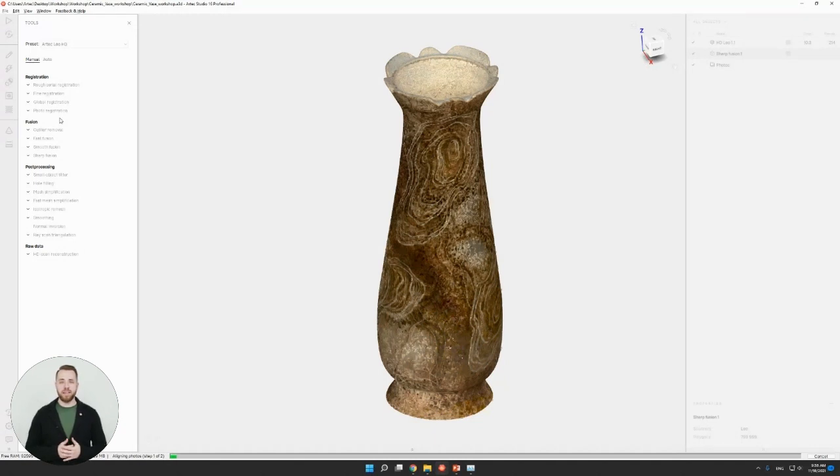The second setting is the descriptor preset. It can be either high or normal. And this setting controls how the algorithm processes pictures. And the rule here is for objects with plenty of texture features, use high, and for the rest of the objects, stick to normal. So this setting defines how many features will be extracted, but at the same time, all these features need to exist.